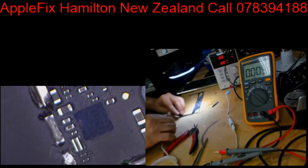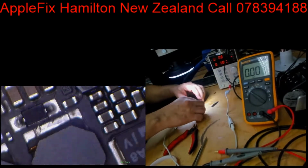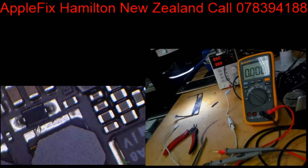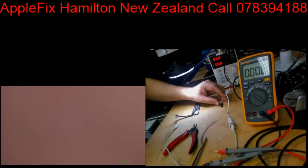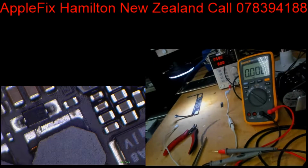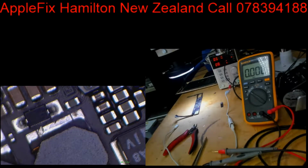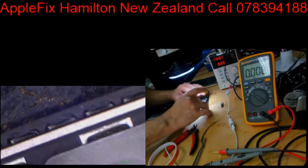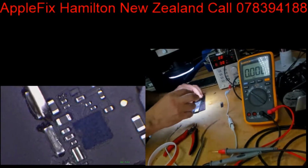So we will remove the U3500 and see. There could be one more thing that might be faulty, which is the charging port, but the charging port is usually either transmitting the current or it's not.